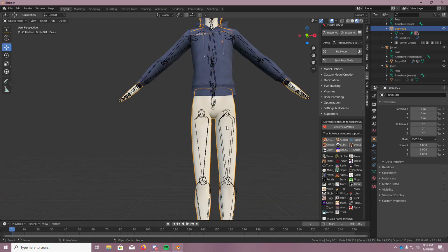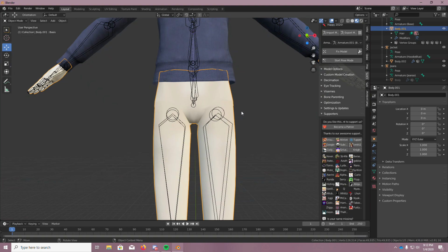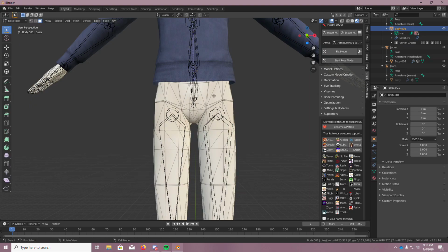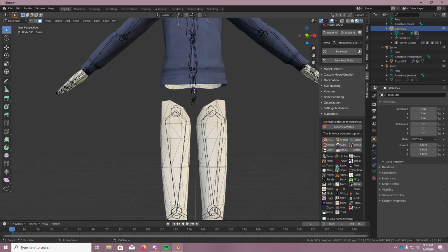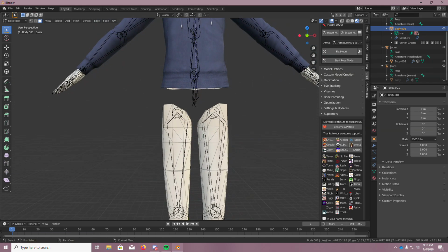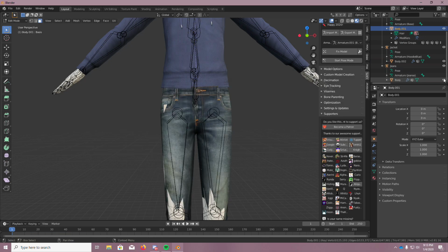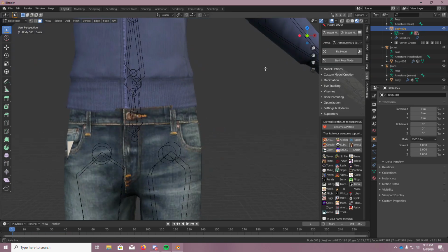Now what we're gonna do is go ahead and look at the pants. So I was gonna hide the jeans real quick, and ooh, yeah, we don't want to see that. Ew, look, an unanatomical bulge. So what we're gonna do is go ahead and do the same thing we did before. Select the mesh, edit, Control L. And we're going to go ahead and remove that. We don't want to see someone's crotch there at the end of the day.